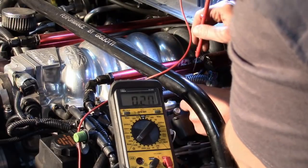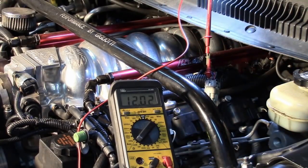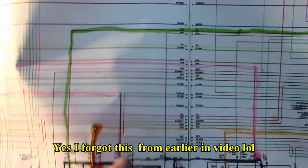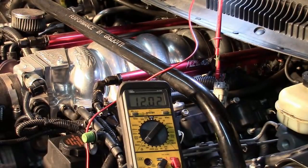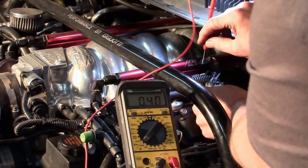I think that's a pink wire. Pink is also good. There it is. There's my positive feed. Okay, so pink wire is going to be my ignition positive that's going to feed all wires. Just to be sure, I'm going to look on my wire diagram. There's ignition positive. Pink wire right there that goes off. It's a pink wire. So you can see I didn't need the wiring diagram for that. I was able to determine it through function. Saves me time.